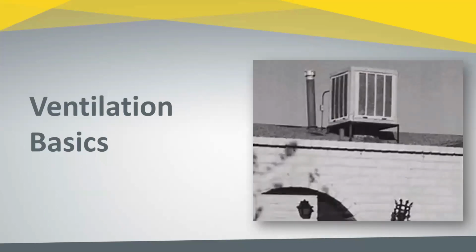So when we look at some of the earlier bases for ventilation design, we recognize evaporative cooling units, which were nothing more than a fixed blower that provided 100% fresh air into a room. Essentially, the air was cooled by drawing the air across a water-soaked cardboard, generally, or a filter pad.